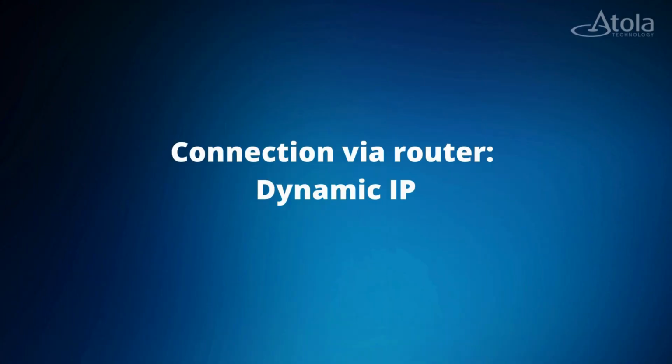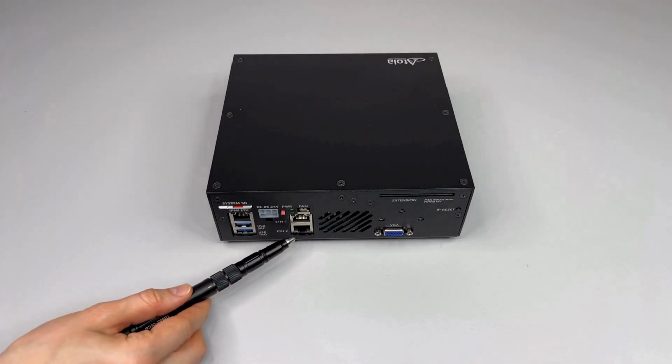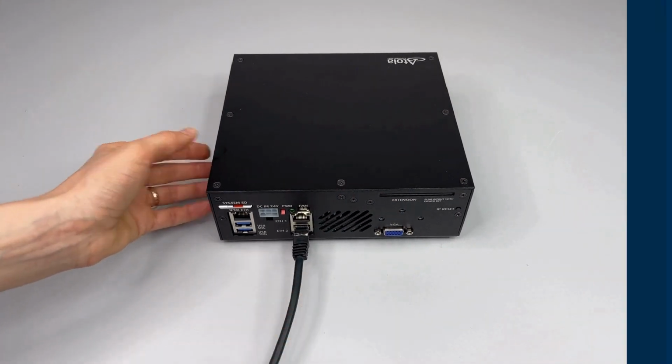If you want to connect the DiskSense unit using a network router or switch, the solution is simple. The Ethernet 2 port of DiskSense 2 is set to automatically receive a dynamic IP address from your network router. To use a dynamic IP address, on step 3, connect a network cable to the Ethernet 2 port of DiskSense 2.